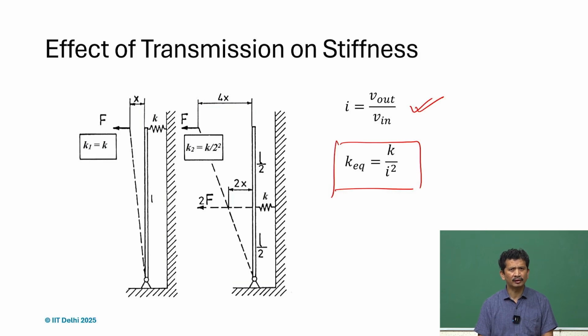Now we can see that there is a huge impact just by moving the spring location. If we talk about general machine design and the load path, we realize that the members placed in the load path, and the stiffness of each and every member, are important.